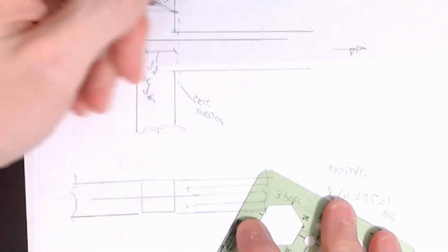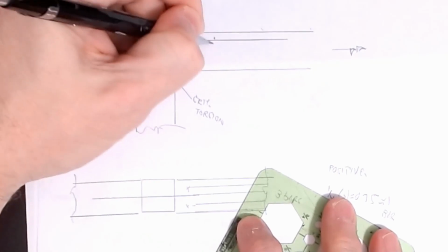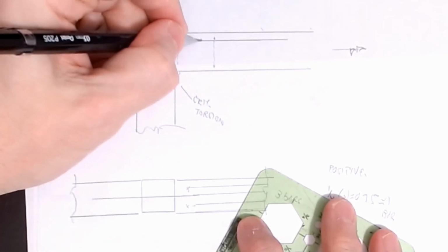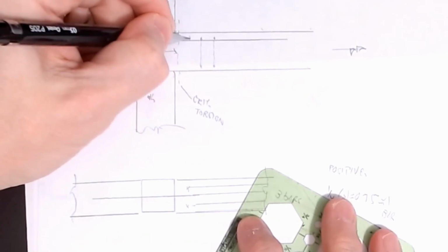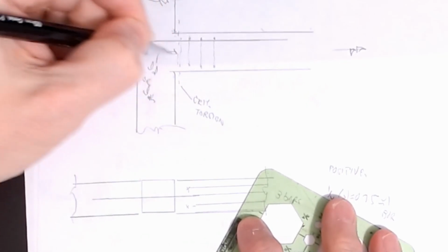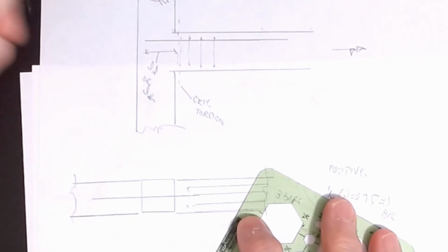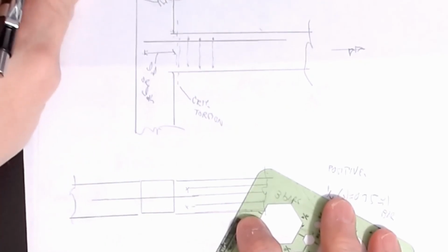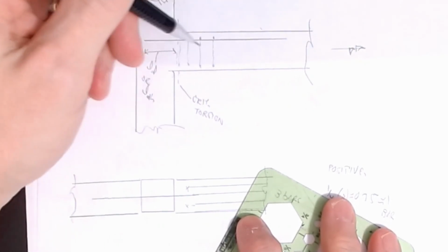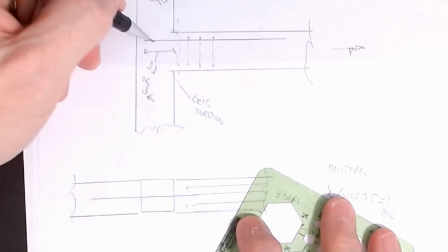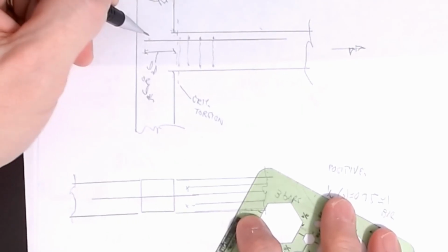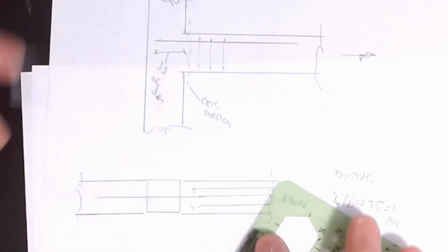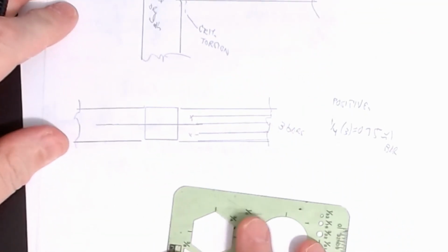Okay. So say I come in and I only need to provide a transverse reinforcement here. You have to continue to supply them all the way over the length of that section, in what they call the clear span. This is the clear span, the beam that's happening here. So I have to keep adding reinforcement for structural integrity, and part of that is, again, to help protect the development length of the bars that I'm continuing through. All right, so that's what we're looking at.